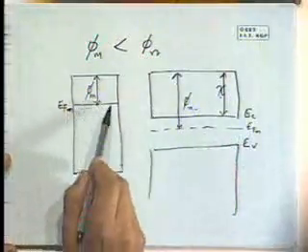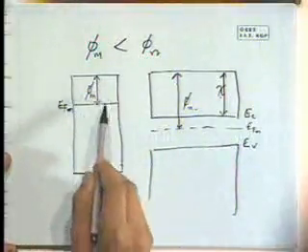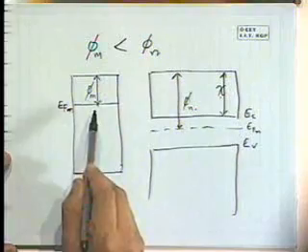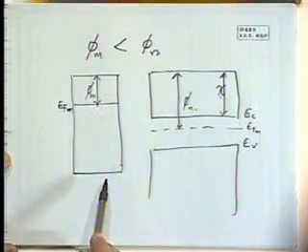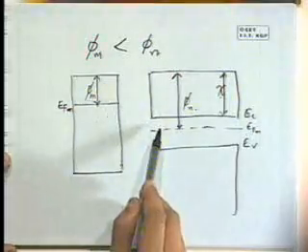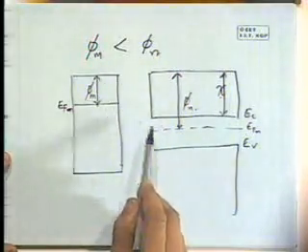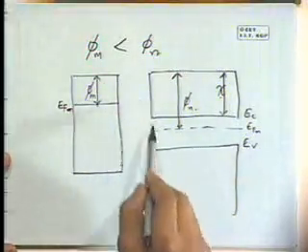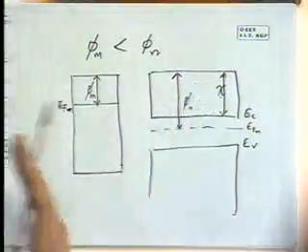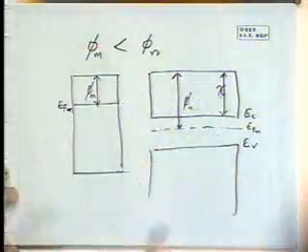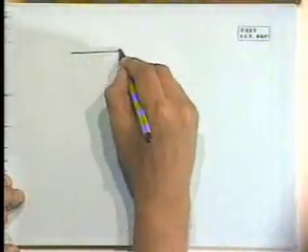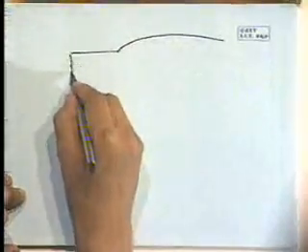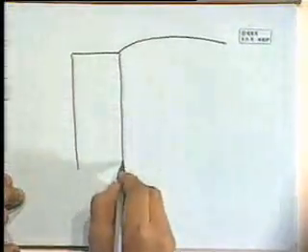When an electron has gone from here to here, effectively it has left behind, from a neutral metal, an effective positive charge. And in the same way here, when electrons flow down to this level, they accumulate here. There is an effective negative charge building up. So we have a field that is set up after contact in this direction. So after contact, the situation will look a little different in this case.